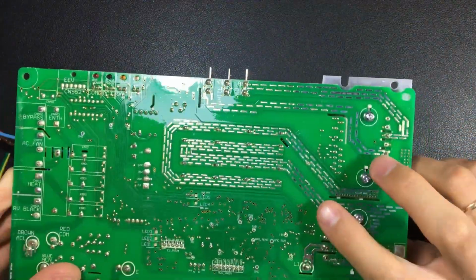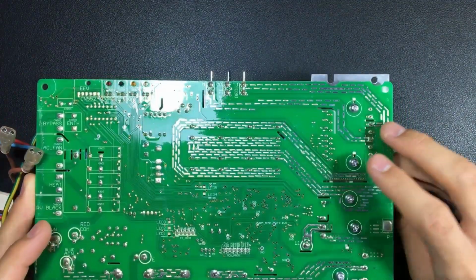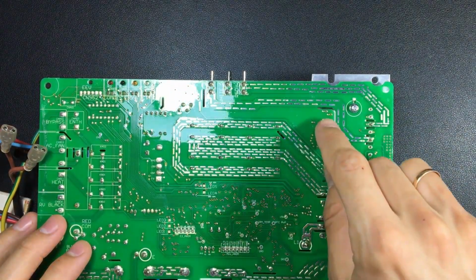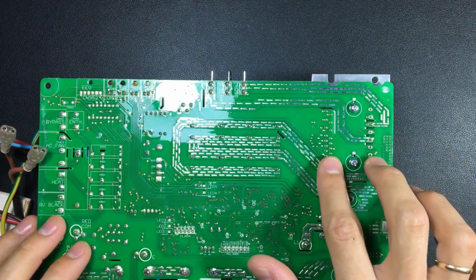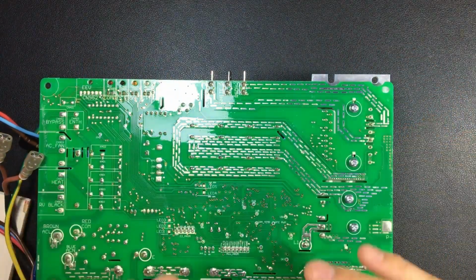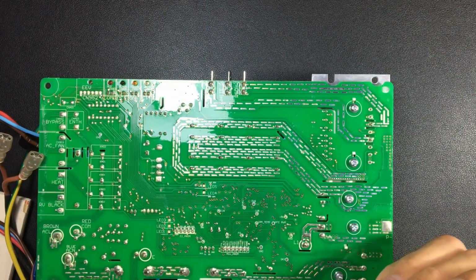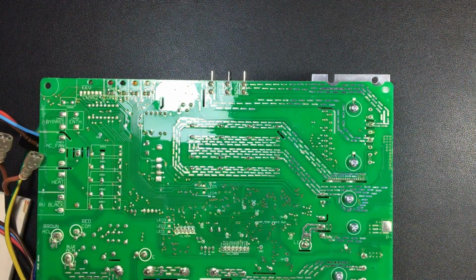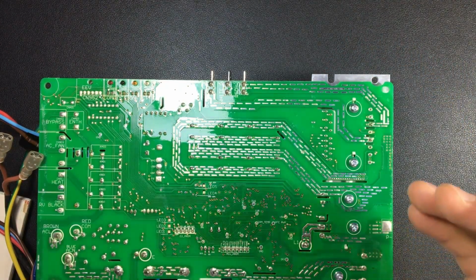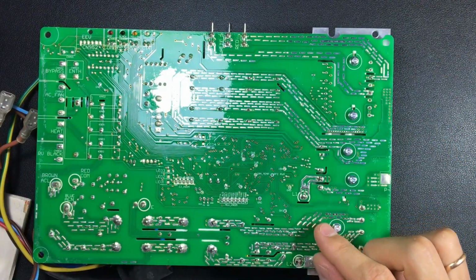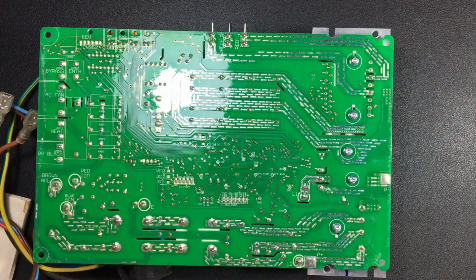So, in these boards, it gets quite complicated. Unless we identify the 15 volt points on the IPM, but for that we would even need to know what model of IPM we have here. So, these capacitors are complicated to check on these types of boards. So, if we suspect that there is this problem, we have to remove the board and test it outside. When we see the test of the complete operation of the equipment, we will be seeing how to measure those 15 volts with the equipment assembled, but in a model that can be reviewed, which is the one I will show you next.